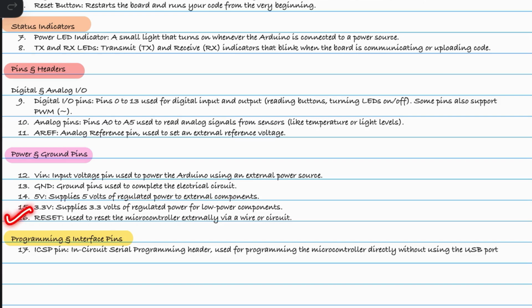Then we also have a reset pin, just like the physical push button we discussed. Grounding this pin with a wire instantly resets the microcontroller. So this helps you to build an external trigger circuit or safety trip wires that reboot the machine automatically.